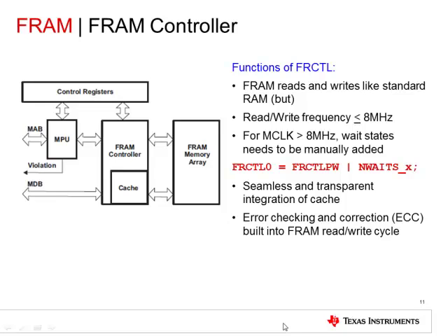However, if none of the words available in the cache are requested, also known as a cache miss, then the required instruction or data is fetched from FRAM. Access to the cache is completely transparent to the user, and the usage of the cache is always enabled. In a typical application, the cache hit ratio is between 66 to 75%.